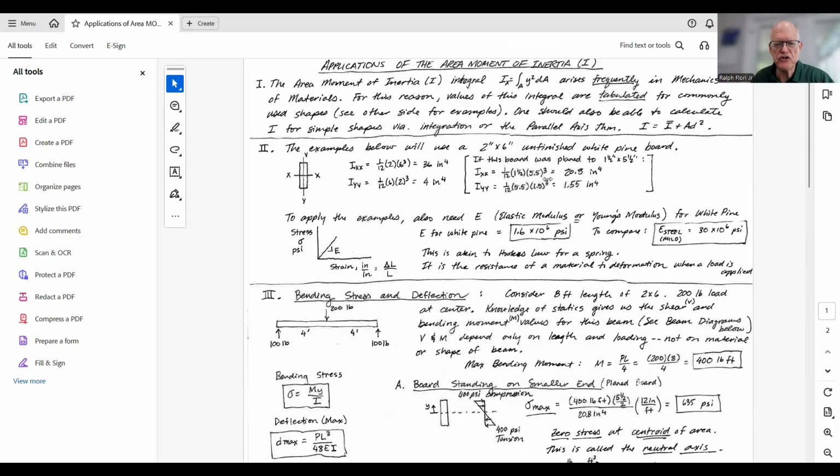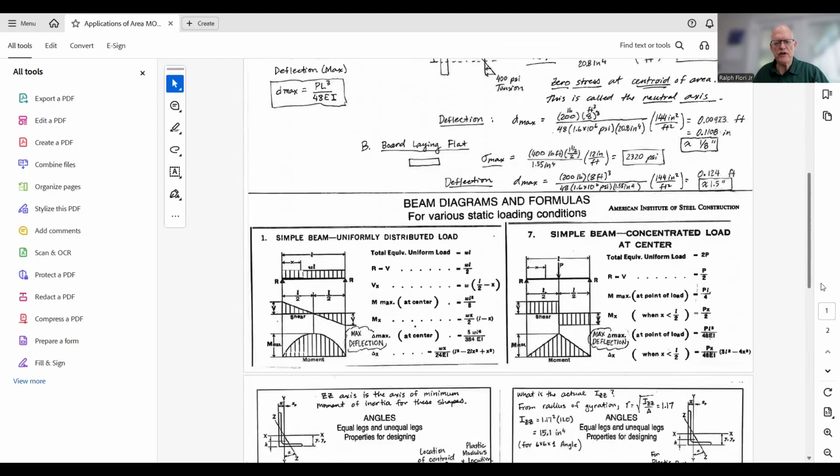Of course, a beam has to have a central web that's large enough, because the web carries the shear stress in a beam. That's another story. You need a web large enough to carry the shear stress and to keep the beam together. But for bending stress purposes, putting the top and bottom flanges further out creates a larger I. That's some background in mechanics of materials as to why we care about area moments of inertia now in statics as we're learning these.